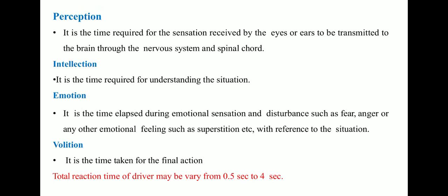Total reaction time. Now all this PIEV takes place inside a human brain. This only takes around 0.5 seconds to 4 seconds. So the total reaction time of a driver may vary from 0.5 seconds to 4 seconds. See how fast the brain takes the decision. Hardly 0.5 seconds to 4 seconds are required.